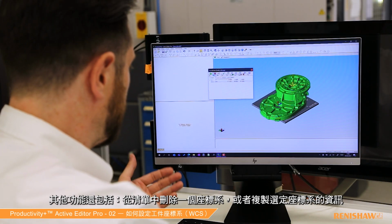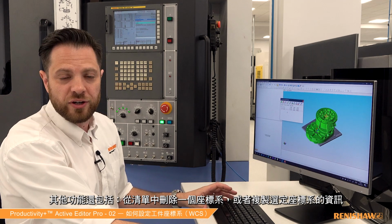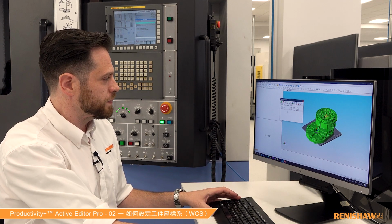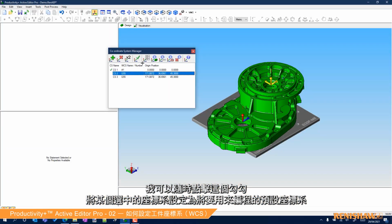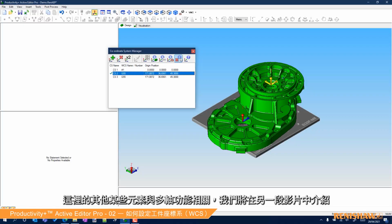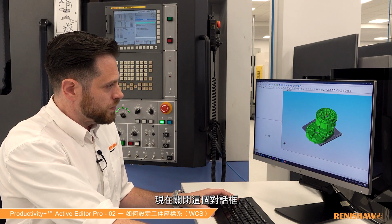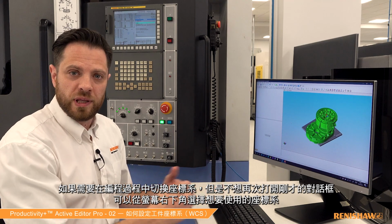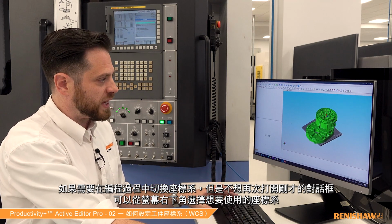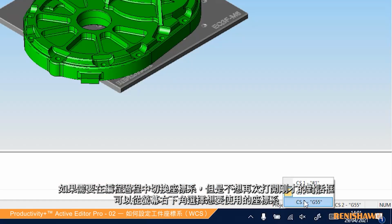Other features we have is the ability to delete a coordinate system from the list, or we can duplicate some of the information in the selected coordinate system. At any point, I can hit this tick, and that's going to set the coordinate system as the default one that we're going to program with. Some of the other elements in here relate more to multi-axis functionality, so we will cover that in another video. If I close this dialog, and I do want to switch coordinate system in the middle of programming and I don't want to have to open that dialog up again, we can go down to this bottom right-hand corner here and choose the coordinate system that we want to work in.